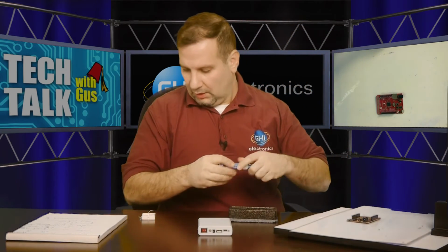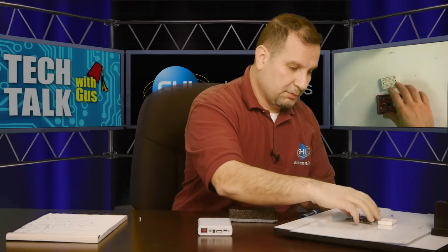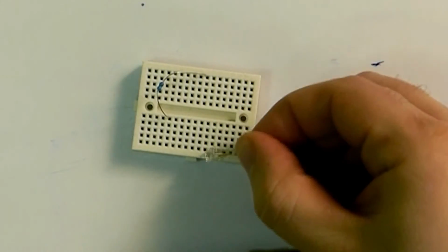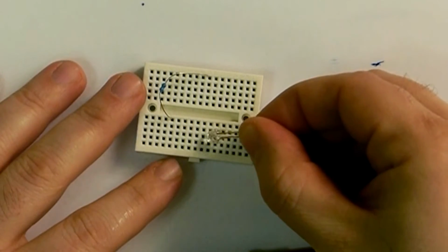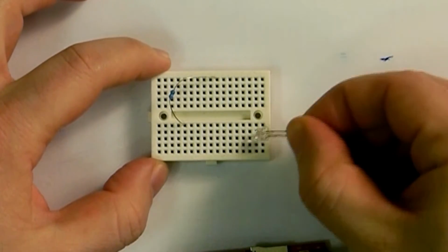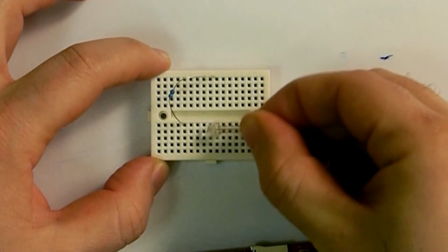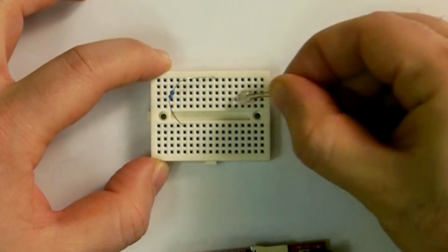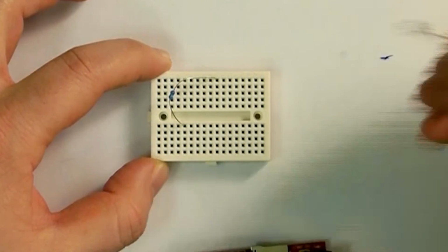Let's get the circuit right here. We have a breadboard. Breadboards are awesome for connecting electronics. What happens on a breadboard is these pins right here, they're all connected. There's 1, 2, 3, 4, 5 pins in each row. Each 5 are connected across, and these are connected across. These and these are not connected, but each 5 pins are connected together.